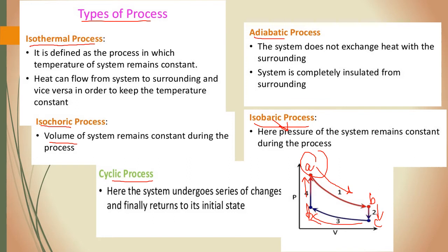Now we are going to talk about processes, thermodynamic processes and different types of processes. First, we will talk about what is actually the meaning of a process in thermodynamics. A process is an operation or a method which occurs in a system when any sort of change or transformation, which can be chemical or physical, takes place. During the process, the system goes from the initial state to a final state through an intermediate series, and this series is called the path of the process.